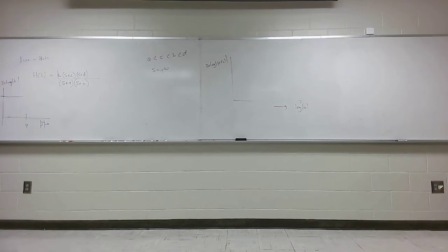Now, when this all of a sudden goes to 1, it'll start coming down at a rate of minus 20 dB per decade. This is kind of important. Y'all remember that? That'd be log of S. So how do you know that? It's a good question. And I want to answer that question. I want you to look here.